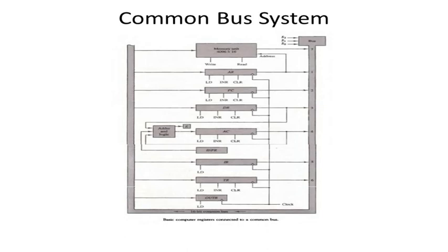So this is connected with this one. So either the addition is performed with the data register and accumulator, or the processing will be performed from the input register. Direct data is coming from the keyboard and added with the accumulator, and again the result is stored in the accumulator. So this is the way the system will work. This is called a common bus system, and these are the explanations given in this slide.